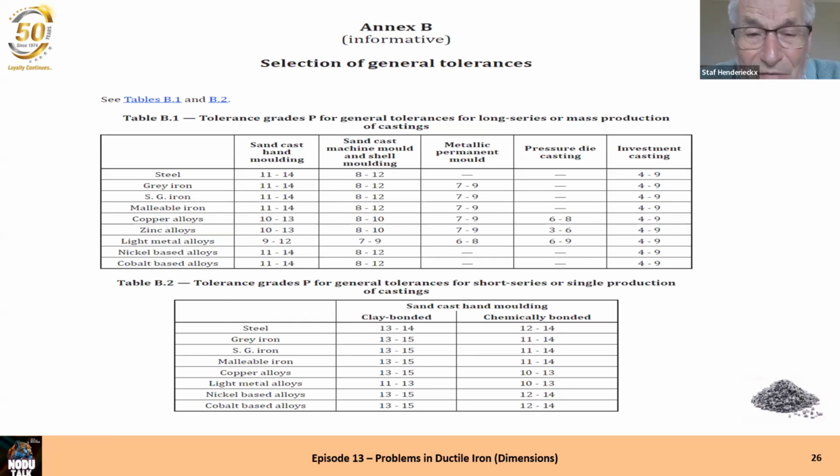If I am involved in problems between a foundry and a customer, then in 20-25% of the cases it's about the tolerance. What happened is that the customer asked for a tolerance, and the foundry said nothing or agreed with it. Then later on, they found out that it's difficult to achieve, because you should achieve it 100% of the time.